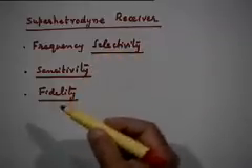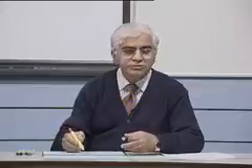to go together. If you for example try to achieve all the selectivity directly at the input to the receiver, the first reaction is that a receiver front end should be a filter, a tunable filter, which you can tune to any frequency. That is the most obvious solution to having a receiver which can tune into a whole band of frequencies. So obviously you should have at the front end of the receiver a filter which will allow the passage of only a single carrier frequency and the message around that.